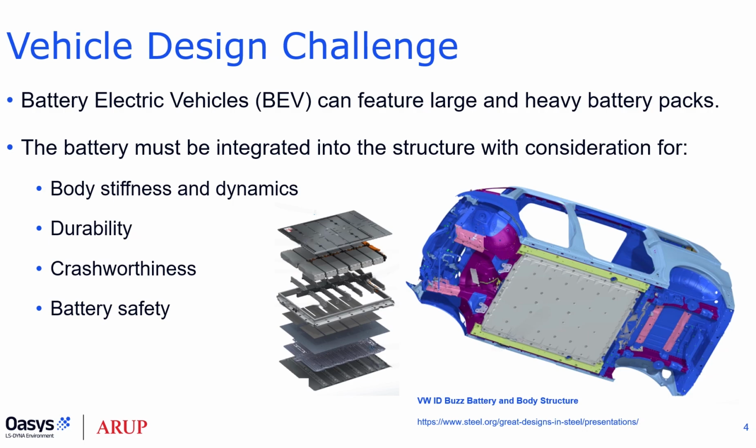From an engineering viewpoint, all battery electric vehicles must accommodate what can be a very large and heavy battery, usually hundreds of kilograms in mass and taking up significant volume. This battery structure must be efficiently integrated into the vehicle structure so that it does not harm attributes like body stiffness and dynamics, durability and crashworthiness. In fact, if the engineering is done carefully, the structure can positively contribute to these attributes.